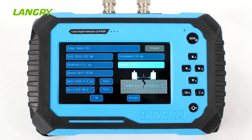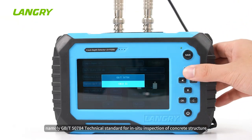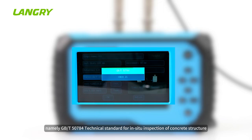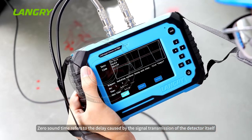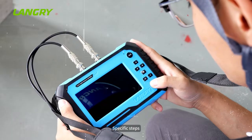Reference: the host can refer to two regulations, namely GB 50784 Technical Standard for In Situ Inspection of Concrete Structure, and CECS 21 Technical Specification for Inspection of Concrete Defects by Ultrasonic Method. Zero sound time refers to the delay caused by the signal transmission of the detector itself, and its value should be deducted. Specific steps.